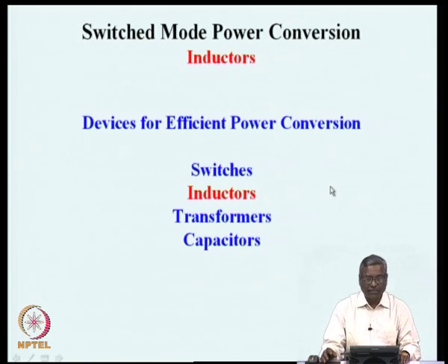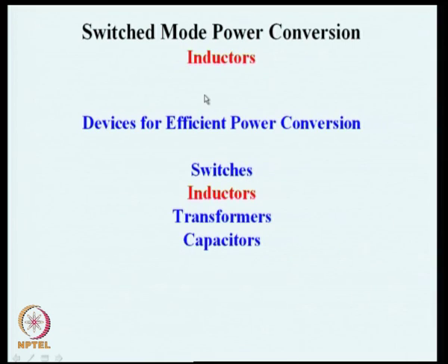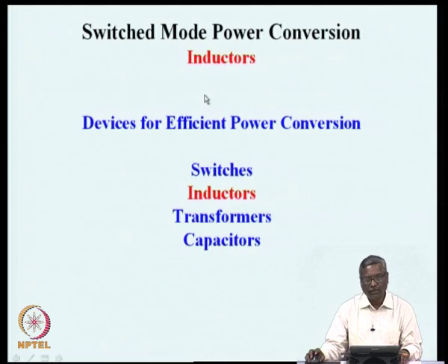Now, what we have seen in the past 1 hour are about inductors, how they are seen as a circuit element, how they are defined, how they are specified, value of inductance and the current through the inductor, and how the electrical quantities of voltage across the inductor, current through the inductor and the inductance value are related to each other through the transient relationship V equal to L di by dt, and then how inductors store energy, and the stored energy is in the magnetic field which is in the magnetic circuit of the inductor, and the magnetic circuit itself has a magnetic material with certain permeability, with certain magnetic length and certain area of cross section across which the magnetic field is established.